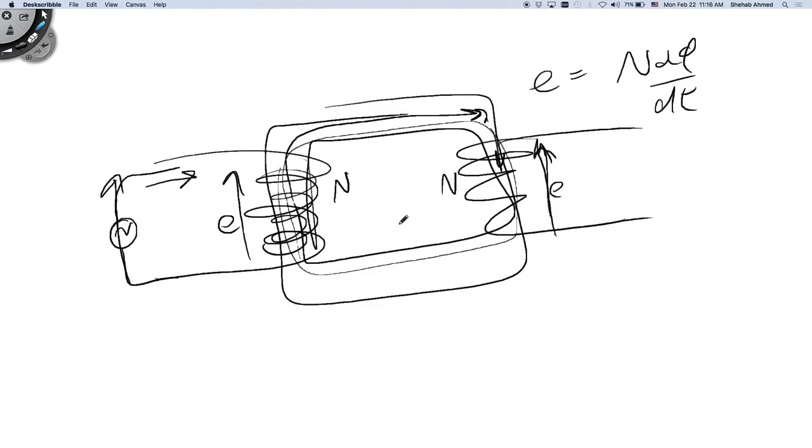It is taking the voltage that you're applying, storing it in the form of a magnetic field that is linking both primary and secondary. Right? And in the positive half cycle it does that, as well as in the negative half cycle. So I'm storing this energy, storing this flux in the air gap in a positive waveform, then negative, positive, negative, positive, negative. And that complies with what I said before about inductors and capacitors.